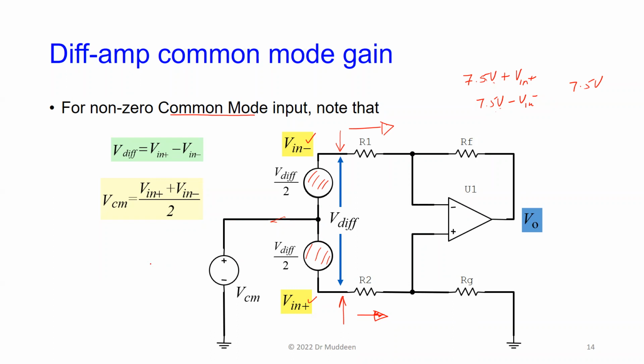Remember, this is what we don't want, we don't want to measure that. This is what we want. Everybody understanding the little model for the source side of things? The differential voltage, we model it as two voltages added together, and we add the common mode voltage to the junction of the 2 of them.